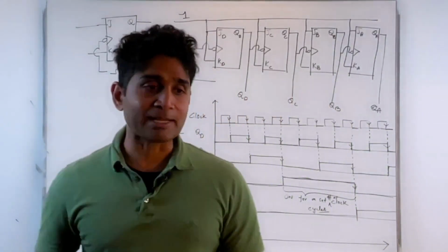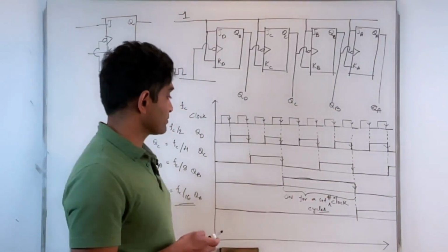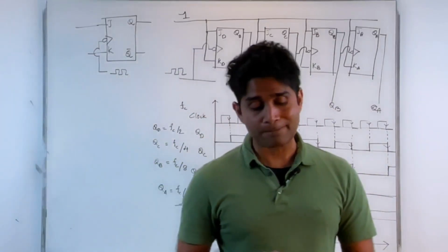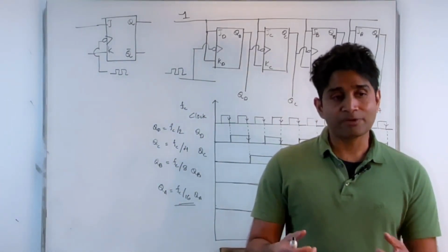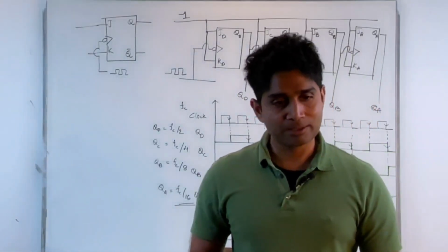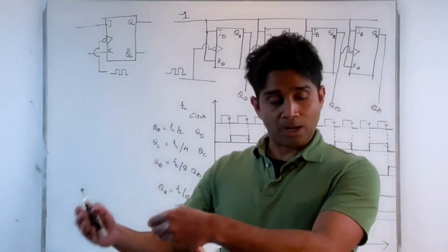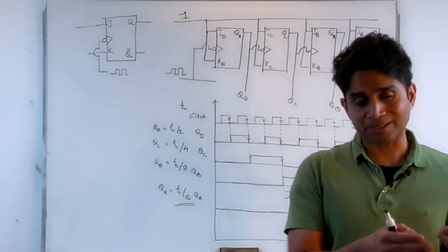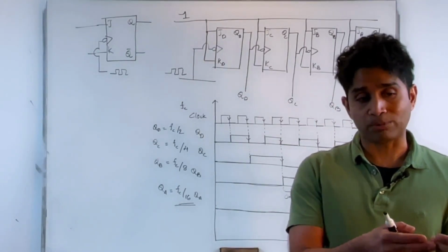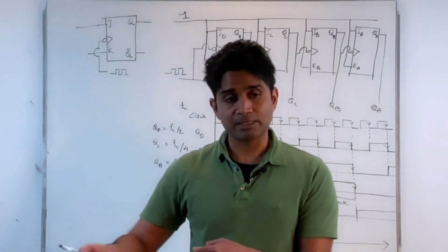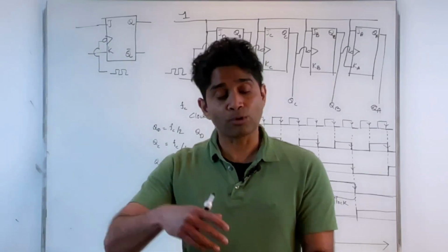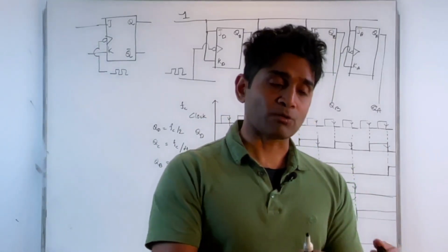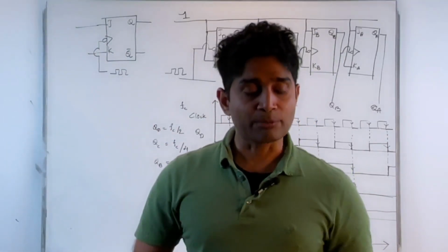Okay, and we'll take an example of situations where we can actually apply this as timing signals. When we talk about a large complex system where you have multiple units connected together, module 1 or system 1 may take n number of clock cycles to finish an instruction. That's the speed at which it's operating, versus a system 2 that may be taking n plus 2 or more clock cycles. And if I want to communicate between these two, that means I need to wait a set number of clock cycles before I can communicate with that other device.